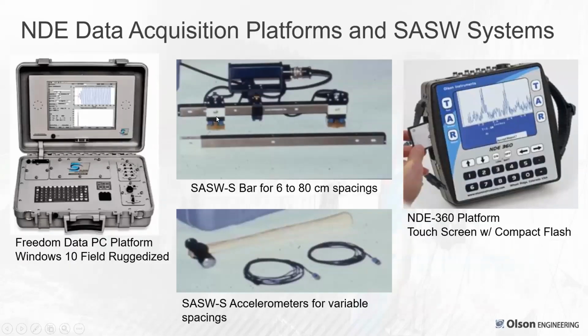So this just shows the equipment up close. There's a displacement transducer. They can vary in spacing on the bar from quite close at 6 centimeters out to 80 centimeters or 2.62 feet. So going from just a few inches to see very shallow and out larger to see up to 7.5 feet deep. If you need more flexibility, you can use small accelerometers, typically magnetically coupled to washers and grease mounted on the concrete. That allows you to have even wider spacings for more distances. The wider you are apart with your receivers, the deeper you can see into the concrete.